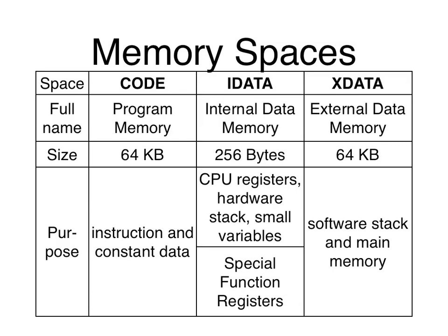Now, XData can be used for software stack, main memory, globals, whatever you want. But if you want to use XData as your stack, then you have to manage that stack pointer yourself, rather than relying on instructions to push and pop for you. If you use push and pop instructions, those operate on internal data space only.